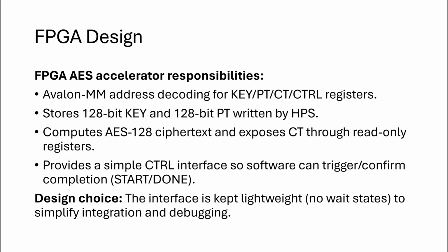And on the FPGA side, our AES accelerator's responsibilities are address decoding for key, PT, CT, and CTRL, storing the 128-bit key and 128-bit plaintext written by the HPS, and computing AES-128 encryption.